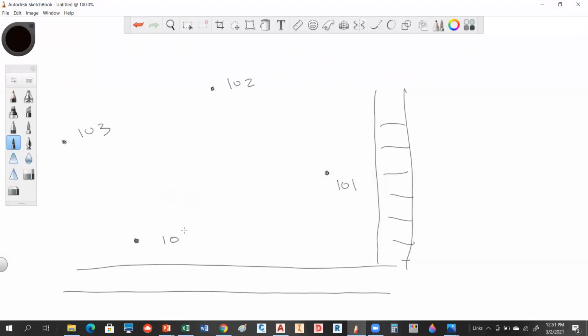And those are iron pins that are in the ground. That was my traverse that I set up. And right in the middle, which is visible from all of these points, is our benchmark, and it has a given elevation on it. So what I'm going to have you guys do is run a loop. If we have time, we'll do the loop through all 3 of these. There's quite a bit of elevation change from here to here, and then from here to here. This is quite a bit downhill, probably a good 30 or 40 feet between 104 and 102, maybe more than that even. And these are pretty much about the same elevation across here, but it's all a hillside that's dropping in that direction.